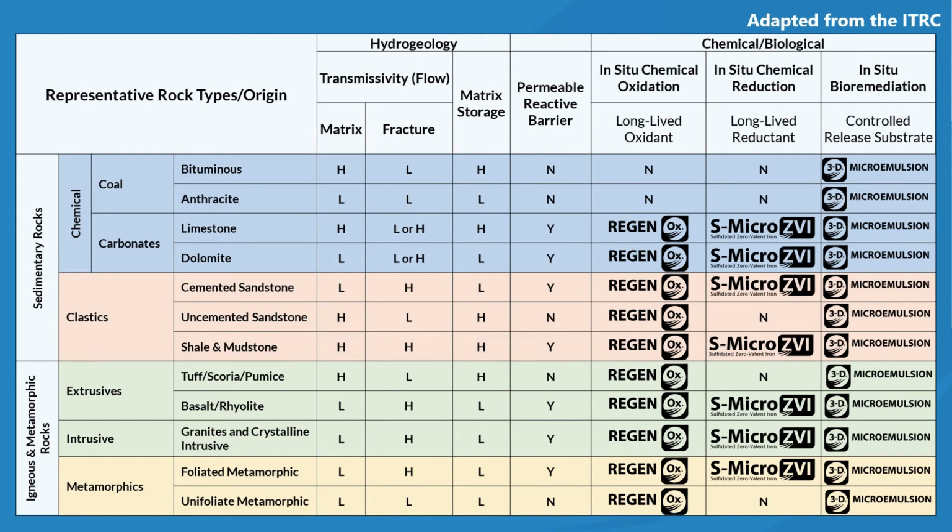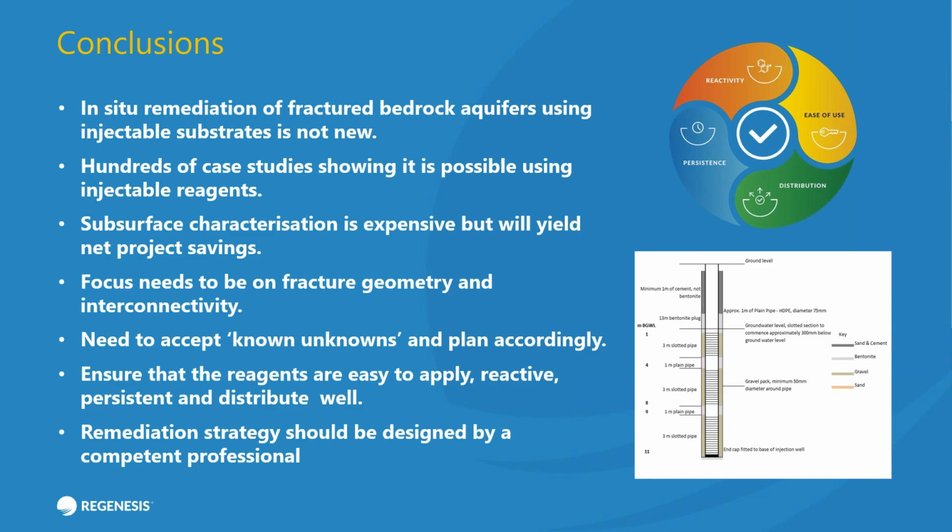And again, this is a third-party assessment, not necessarily of our technologies, but of long-lived oxidants, long-lived reductants, and controlled release substrates. So in conclusion, the in situ remediation of fractured bedrock aquifers using injectable substrates, it's not new. It's been tried and tested many times. There are hundreds of case studies out there showing its possible use. But subsurface characterization is expensive, but will yield massive project savings. Your focus needs to be on fracture geometry and interconnectivity so that we know exactly where to target our remediation efforts.